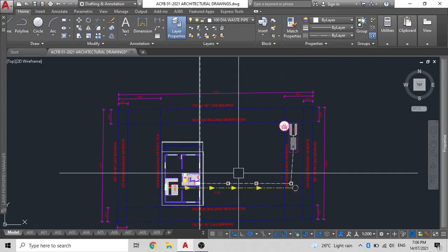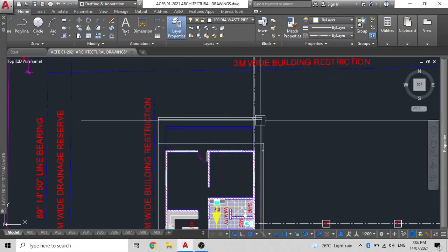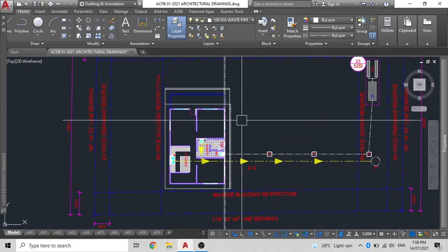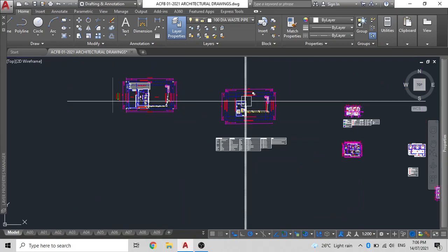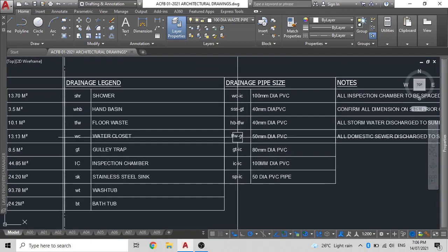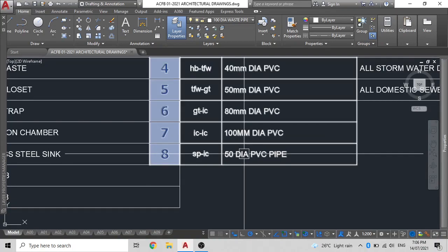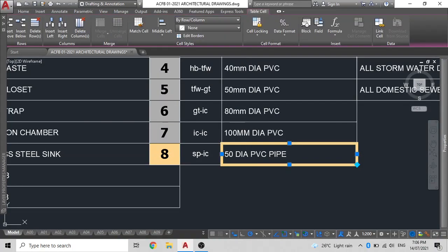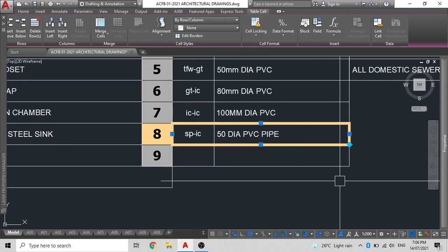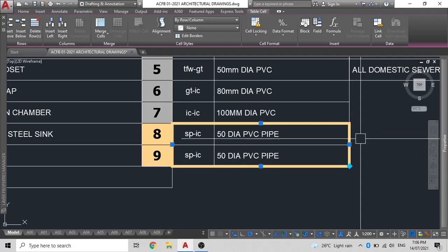Now the next thing that we will create is the direction of flow for the gutters. That's not a very difficult thing to do. We'll just refer to over here, and if we cannot find any, we'll just do our own from here. So we can just create another node, and just to bring that node to this cell, just click on this and bring it down like so.